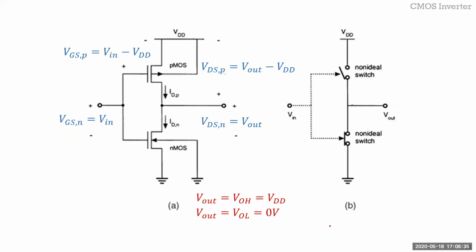Okay. All right, so that brings us to CMOS now. As I said, in the resistive loaded one, in the NMOS, the biggest problem people faced, and that was really one of the major reasons for the birth of CMOS, is the static power. They wanted to kill it, because let's say you're running a circuit at a very low frequency and you want to spend power only in charging and discharging. You don't want to spend any other power. Whereas in the resistive loaded one, like the one before, you're basically drawing current half the cycle. So that's not desirable. So that's where CMOS came into the picture.